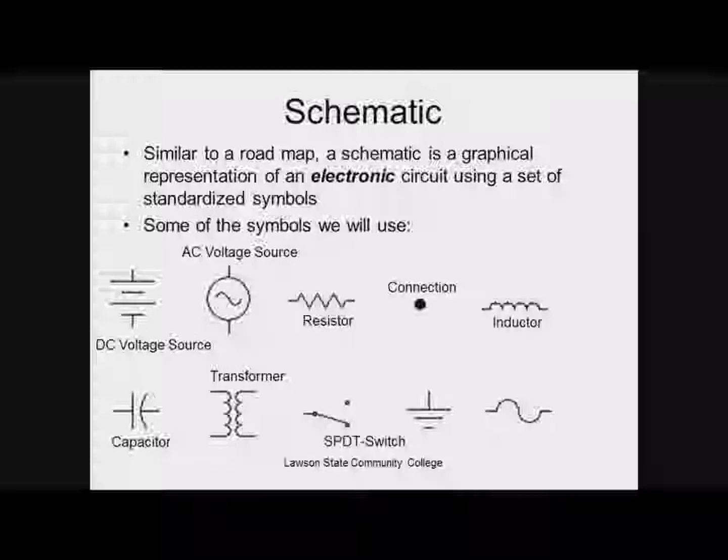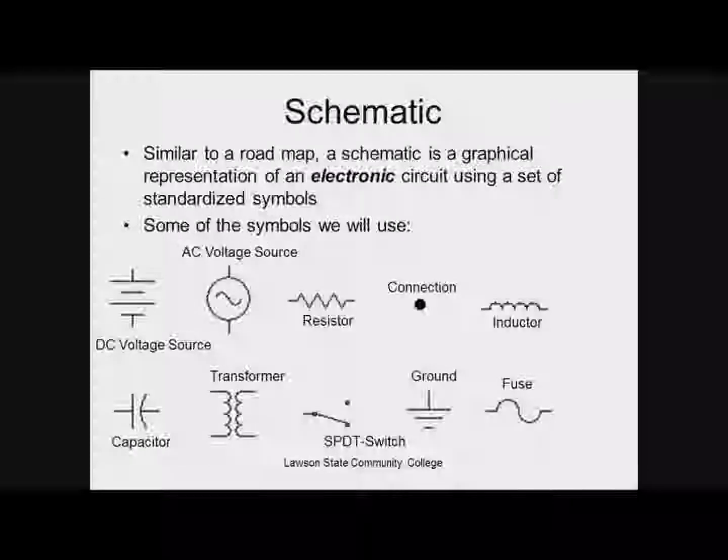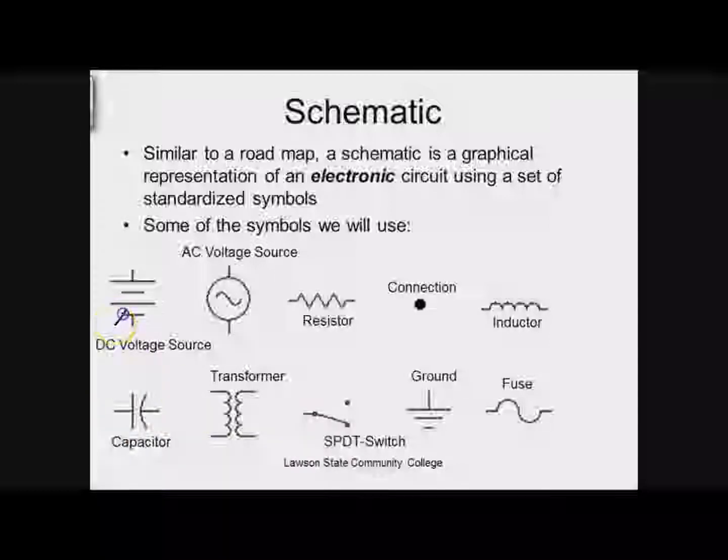But you can ask almost anybody, even in the trade, and they'll ask you what this symbol is for, and they'll say a battery. But if we come over here on any of these symbols, except for the wire, and if they put an arrow through it like that, that means it's adjustable. So if you take like DC or those courses like that, those power supplies are what we call variable power supplies, which means you can do what? You can adjust them over range.